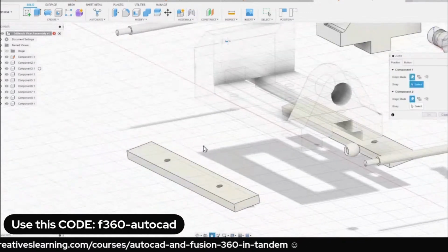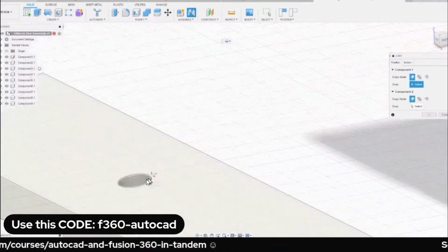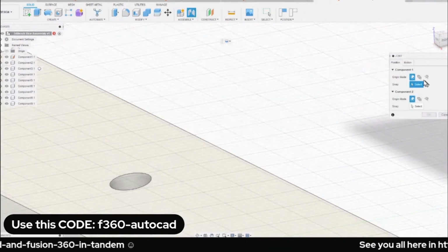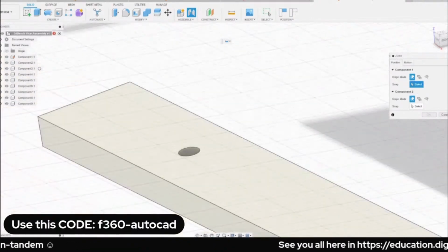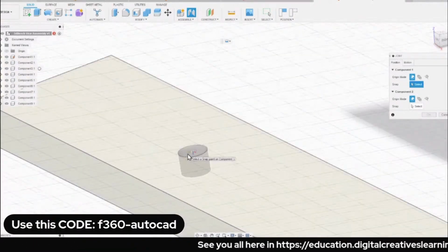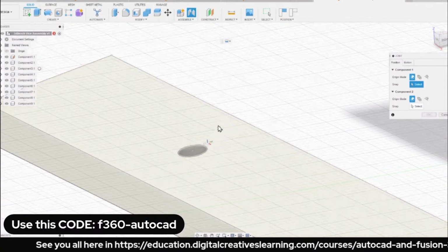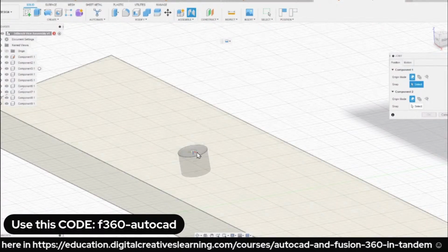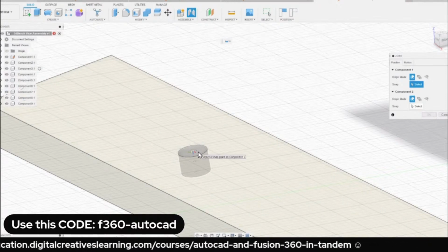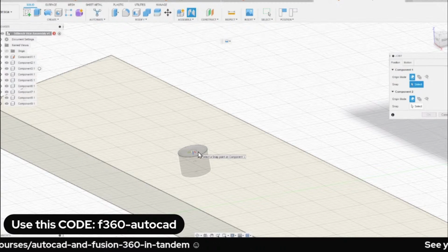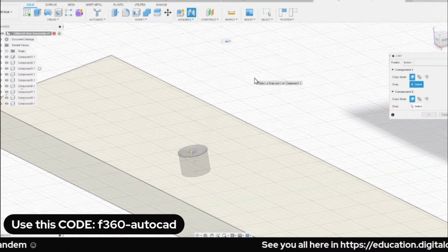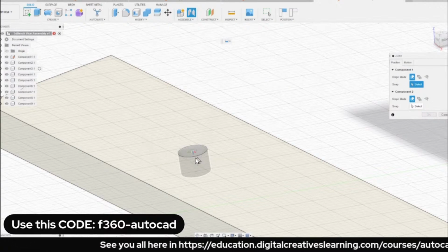So to understand this more, I'm going to define our joint origin snap point, otherwise called the joint origin. Notice if I hover over here, we're highlighting the cylindrical face. If I hold control and move my cursor out, it means that we are locked on this face.